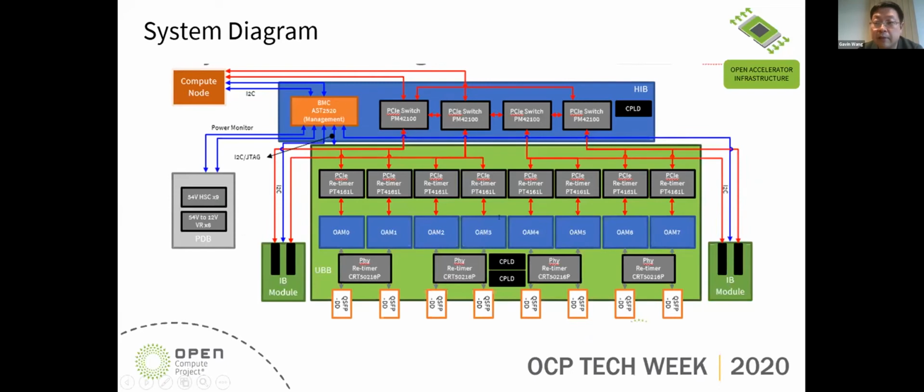This is our system topology. We just use 4 PCIe switches. Each switch downlink can support 2 OEMs, and each OEM can support a dedicated expansion, the QSFP-DD. You can use this port to do some scale out.